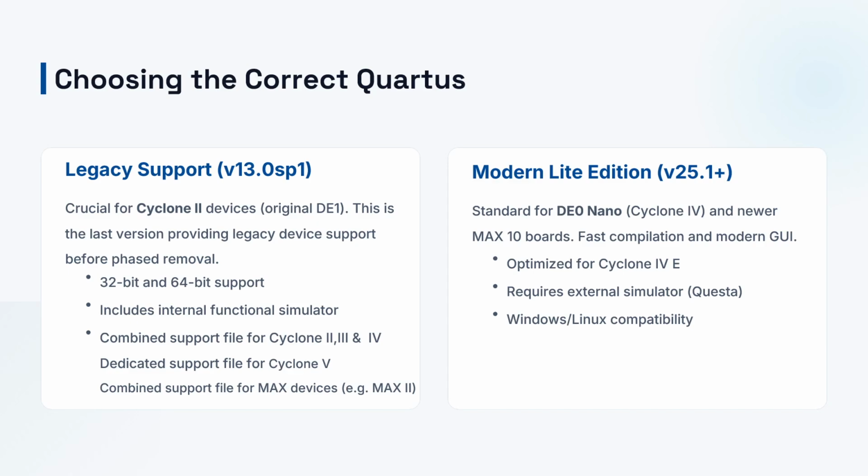However, if you are using the DE0 Nano, which features a Cyclone 4, you can set up the modern Quartus Prime Lite version 25.1 or latest. Note that the modern versions offload simulation to external tools, while version 13.0 Service Pack 1 also includes a built-in simulator.